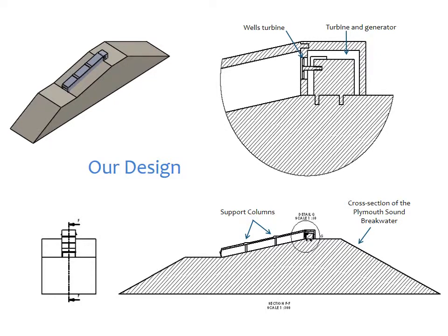The turbine housing features 2 vents on either side to allow the air to flow in and out of the system, preventing choking. These vents have shrouds to help stop water getting into the housing. Inside the turbine housing is the turbine and generator, and attached to the turbine is a Wells turbine with a diameter of 1.2 metres, which is almost flush with the hole in the housing, encouraging air to power the fan rather than escape around the sides.